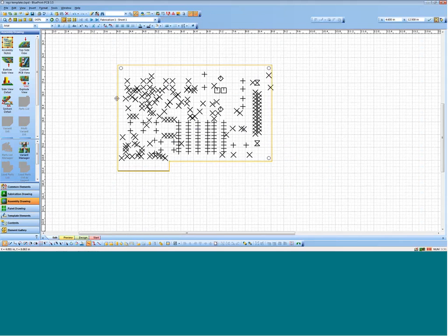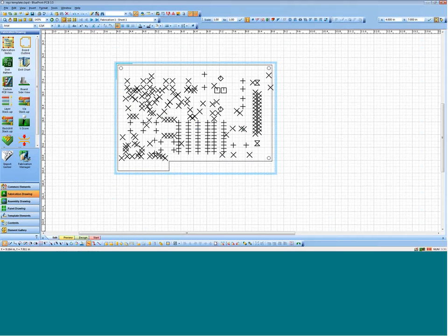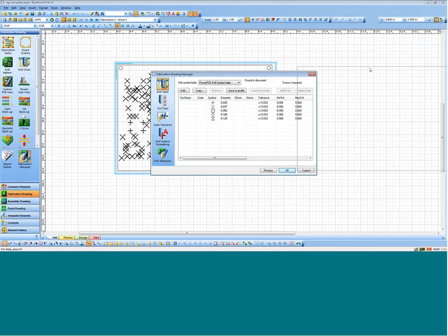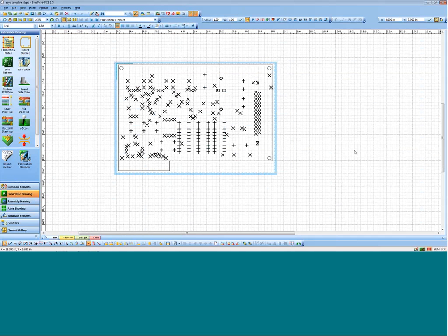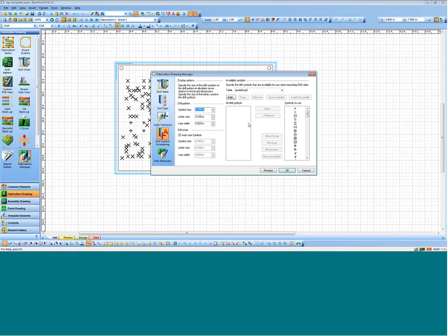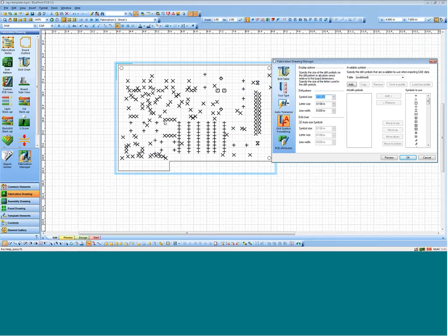So here I have a drill pattern. Okay. Well, one thing I noticed right away is it looks like all those X's are a bit busy. They kind of overwhelm everything. So if I really want a legible drill pattern, maybe I'll come over here to my Fabrication Manager and reduce the size of the symbols. So it's not like I have static symbols that I can't change. I can change not only the symbol itself, but I can change the size of the symbols. I can even set up patterns how I want this to populate.